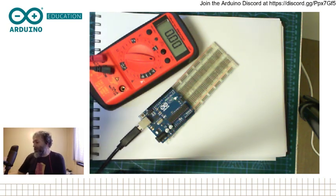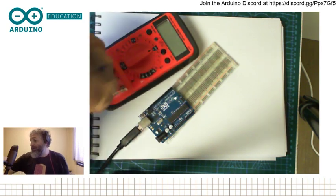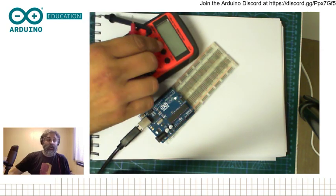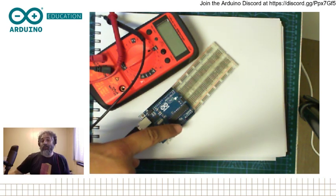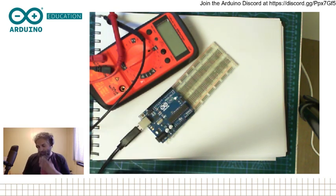that is used to eventually power small sensors that might work at 3.3 volts. The 3.3 volts on Arduino Uno is not giving you a lot of current, so you should not really use it to power anything big at 3.3 volts. You can power up small circuits like an IMU that works at 3.3 volts, for example, but not a motor. While the 5 volts being here, you can really use it to power up, for example, a small DC motor.